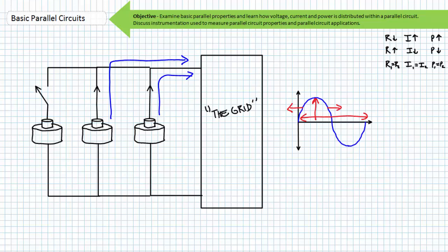AC is its own strange animal, but consider at the moment of synchronization, the grid having one value and the generator being brought online another because of one of three undesirable scenarios. 1. The generator could have the correct frequency and the correct phase shift, but the wrong magnitude. At the moment of synchronization, a differential would exist. 2.